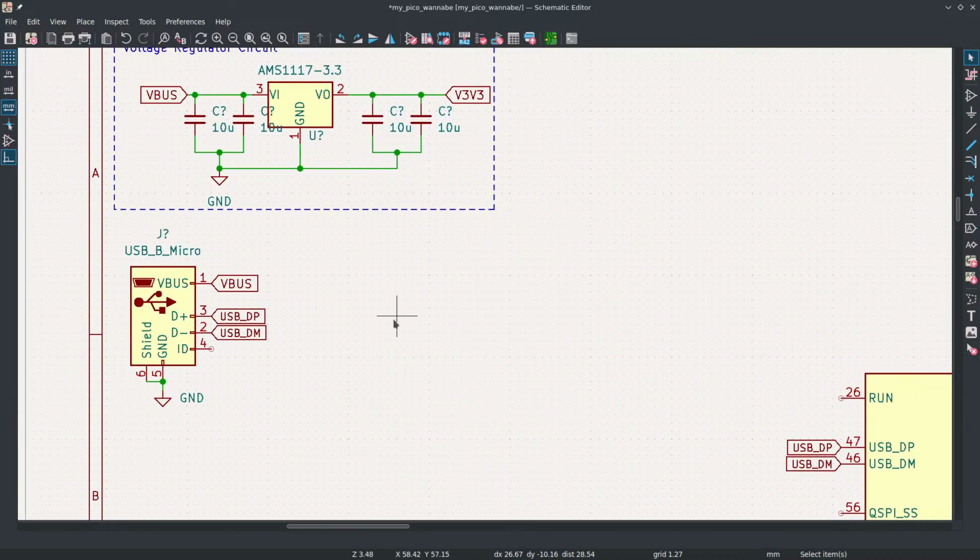I like it, thanks. You don't want a bunch of different names that mean the same thing floating around. You try to leave breadcrumbs for yourself when you come back to the design in a week and you don't remember anything. You're like, is USB VDD the same as VBus? Now you have to go check, or you made them the same name and it's not a question that comes up.